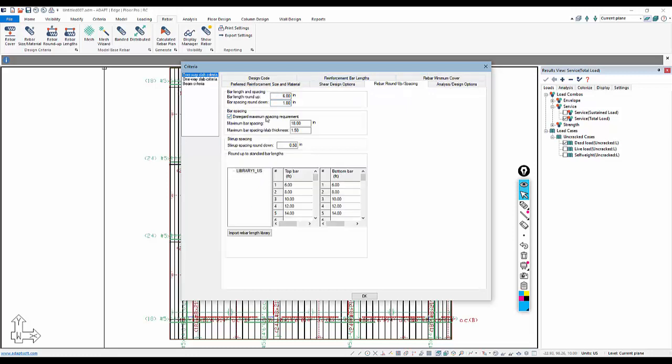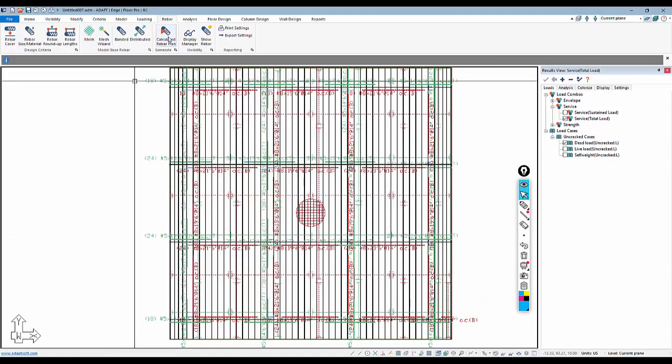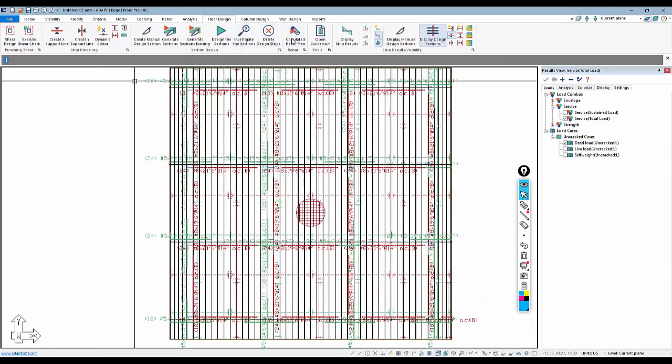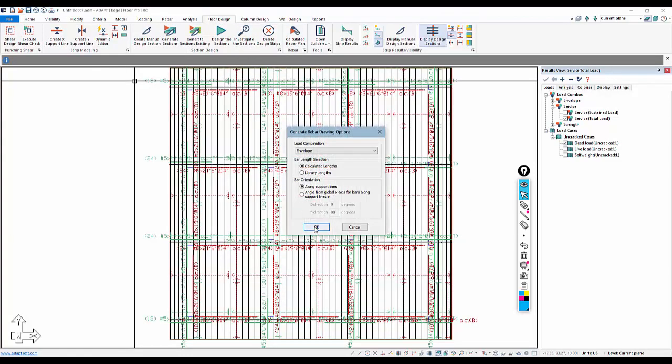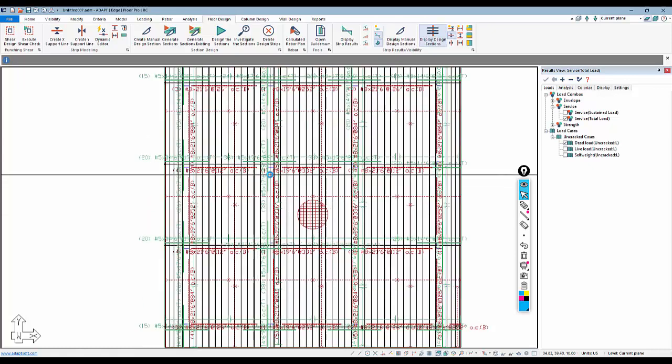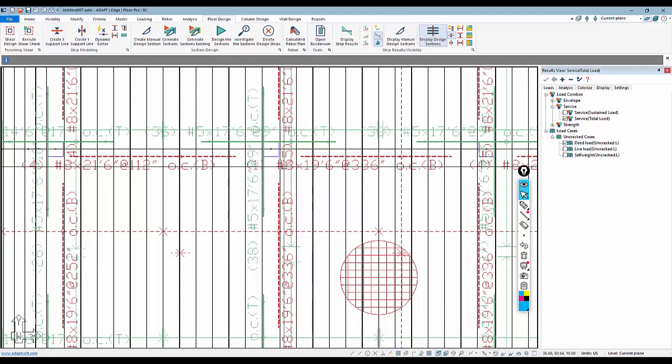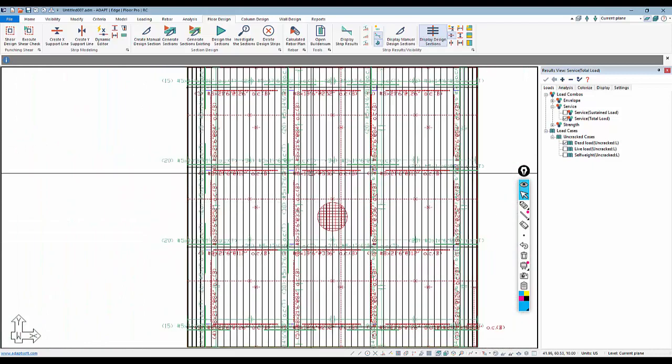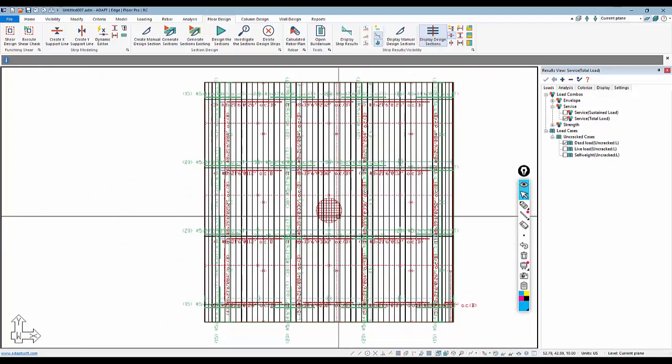Select disregard, meaning turn this option off. If I come back and then regenerate the plan, we're only going to need one number 8 bar there shown here. So that's how the minimum reinforcement and the spacing reinforcement and even strength reinforcement are all working in an RC slab when you have the spacing option turned off or on.